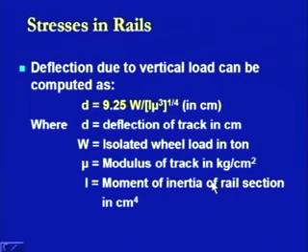This is one aspect, but not only stresses are induced. There are other conditions too: deflections may also be induced because of the loading. When deflections are induced because of the loading, we have to look at the total amount of deflection induced. If the deflection is more than the permissible value, it will cause the failure of the system. Therefore, this value is to be calculated.